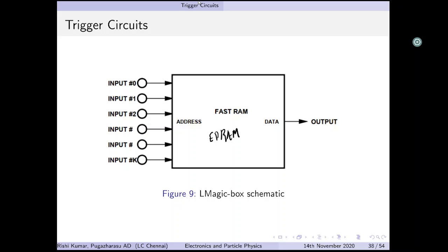And sometimes it uses current generators to power itself, and each active input is sometimes powered by the current generator, which might result in some excess current. But the excess current is directly proportional to the number of active inputs, and if you use a proper counter in one of the spaces here, you can effectively calculate the excess current to a certain degree and filter it out later on, or when you send it to the discriminator, that would cut it off accordingly.